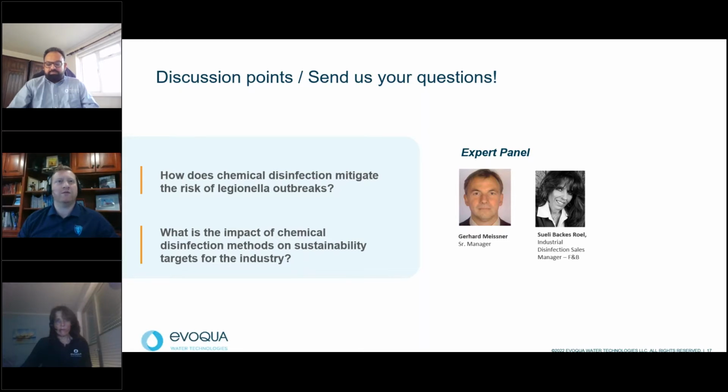Yeah, OSEC technology has some striking advantages with respect to safety. There are no dangerous precursor substances involved. It's just water and salt that is transformed by means of electricity into the sodium hypochlorite that you immediately need for your process. So you just produce what your process requires, which minimizes operator risk.